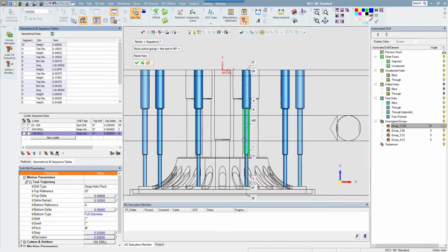So now here comes the sequence part. I'm going to have other core blocks that have this same type of back drill. They just might be shorter, different heights of block, things like that. But the diameters are going to be the same. So why would I program that every single time? Well, with sequencing, you don't have to. So that starts up here.